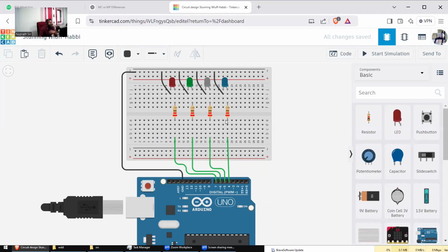If it hadn't been for that, you would have to use a lot of wires. By making a common ground, you can use a smaller number of wires, as well as keep the circuit very simple. Okay, you can keep the circuit very simple. Now, for this particular kind of LED setup I have here, just with 4 LEDs, but you can go up to maybe 10 LEDs or 7, 8 LEDs. You do that later. But I'm not going to do the circuit for you. You try that one. In the class, we will build it the next day.